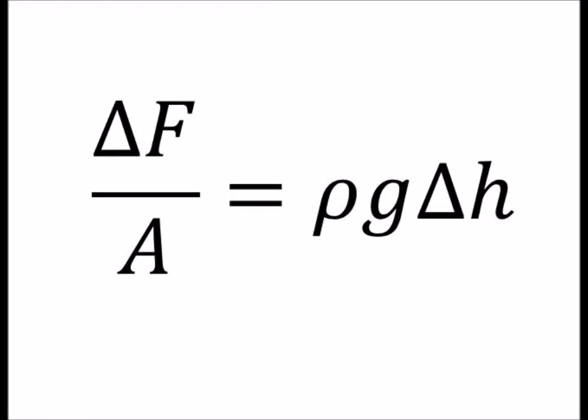Here is the fundamental equilibrium equation the system tries to achieve at all times when water is involved in consolidation and settlement, where the change in pressure of the beaker as the weights are added is represented by force over area, and the change in height due to pressure in the pressure gauge is represented by density times gravity times height.